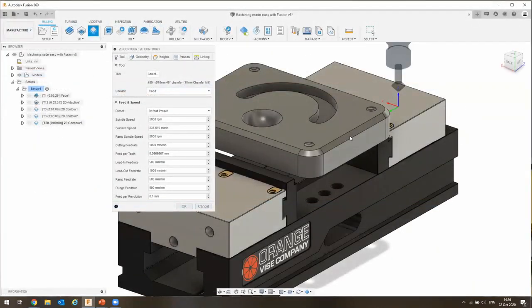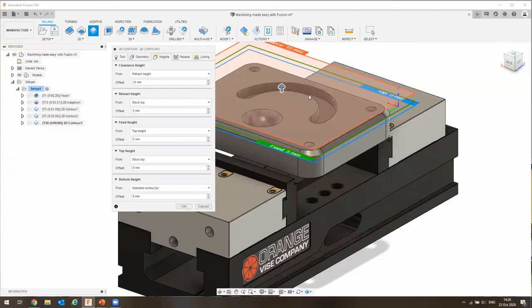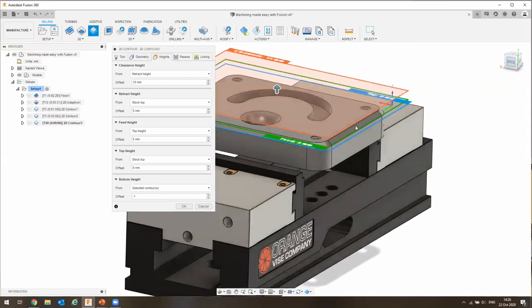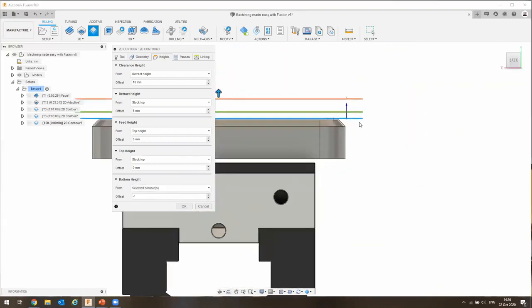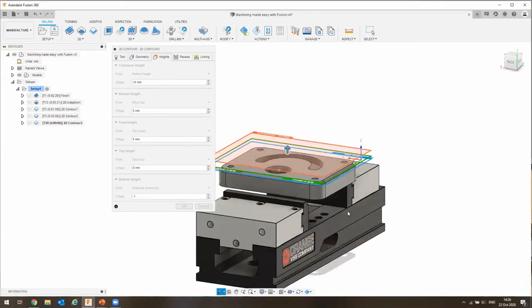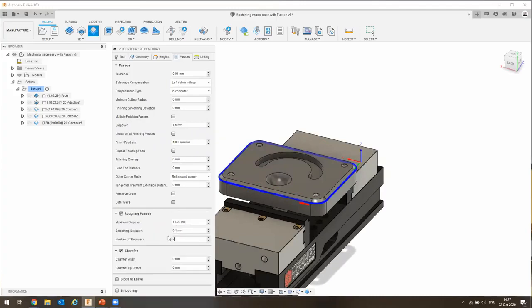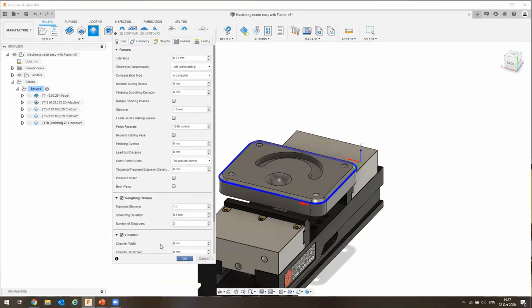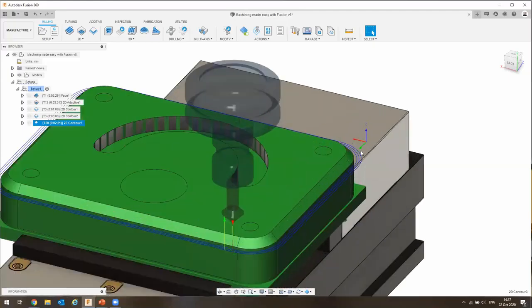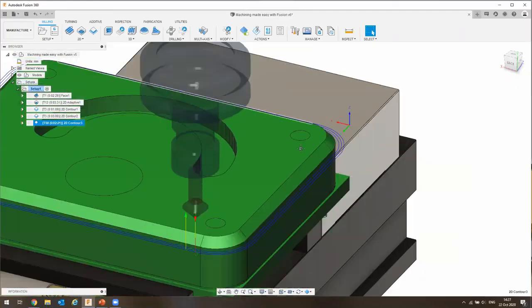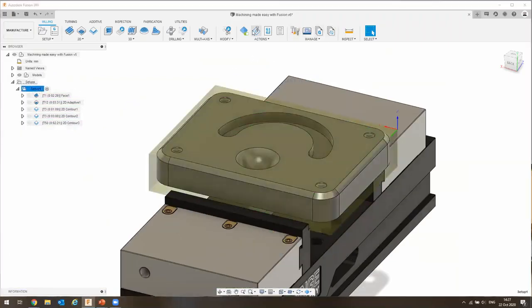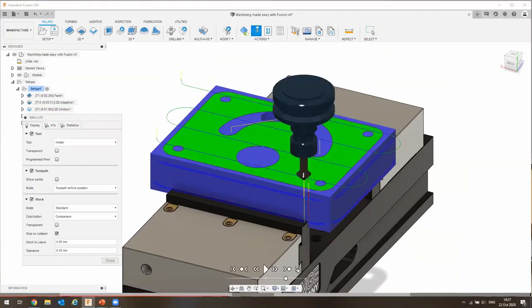And I do need to do a little bit of a height adjustment. So the height is obviously that bottom of it, but I'm just going to say -1. And all that is for is I want my cutter to stop a little bit underneath here. So I don't need to change any other settings. I might want to do the roughing passes like I did. So I'm going to say roughing passes, put it at 2 with the same 1.5 step over. So, okay. And as you can see, it's then doing 1, 2, 3 loops around to get the part. So if I just do my simulation, and you don't need to actually play all of them. Like I said, you can just say go to the end.